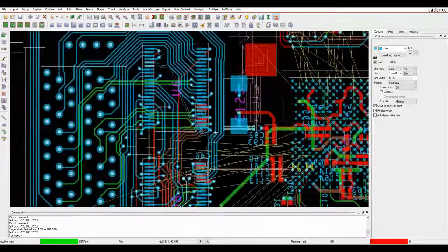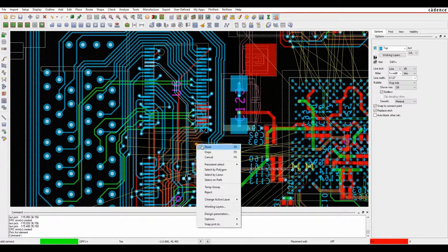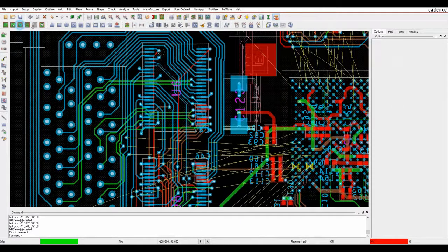So what we'll do is we'll just pan down. If we're not happy with where we're going, we can obviously just go back along the scribble path until we're happy, and we'll guide it all the way down to where the vias are. When I click to confirm, the routing is then completed, and I'm done. We'll just go back into etch edit mode.